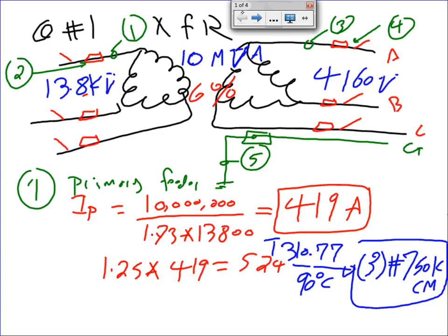So long story short, big introduction. It's an ungrounded system, but I need a grounding electrode conductor for it. Why? Because if I have a first ground fault, no problem. I get an alarm that there's a ground fault on the phase. When you have time, on a weekend, when the assembly line is down and nobody's working, go fix it. But you don't interrupt the process.